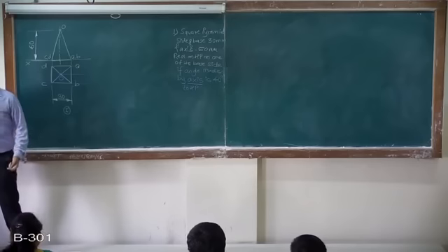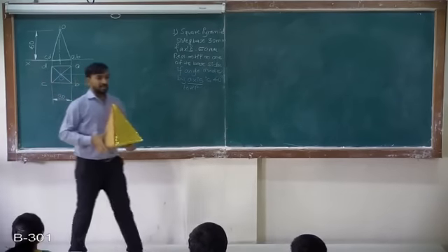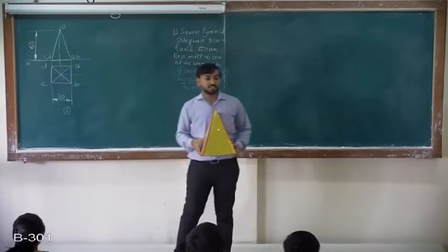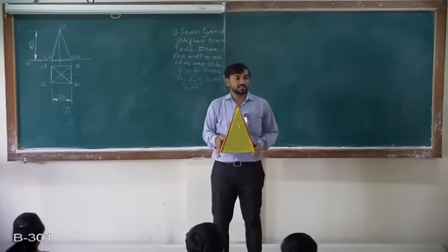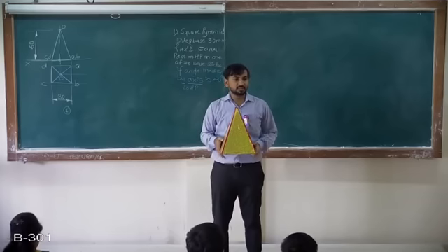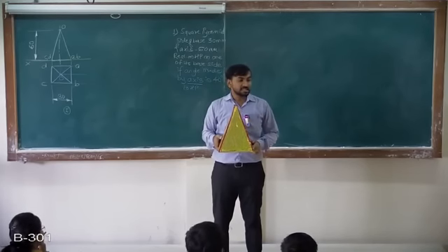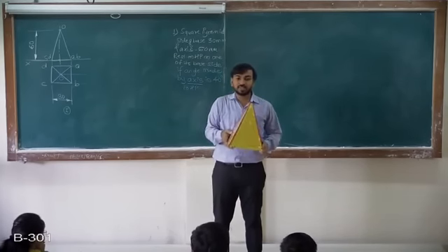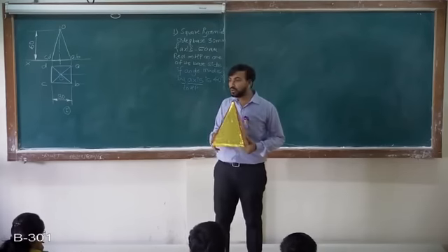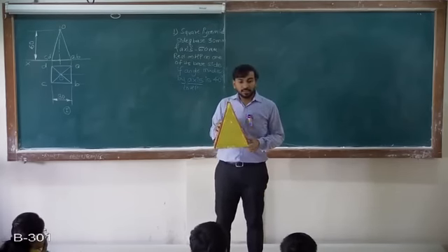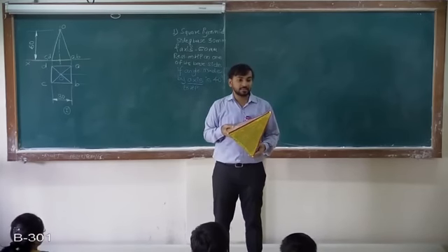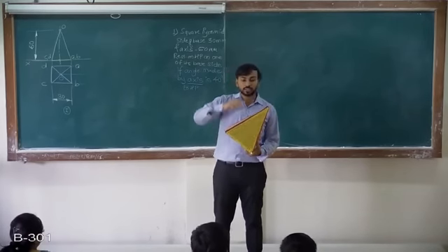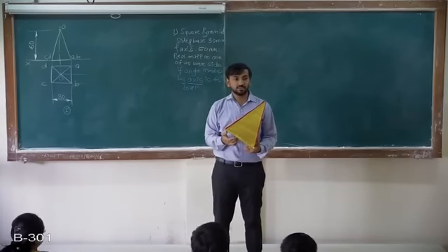Now see it. The second type or second condition for this. This is a square pyramid. The first condition is constant: the square pyramid resting on its base on HP. It is inclined to HP, so that is the kind of second condition that may be given. Now we are saying it is inclined to HP, so that the axis is making an angle. The axis is the apex joined with the center of base, right?